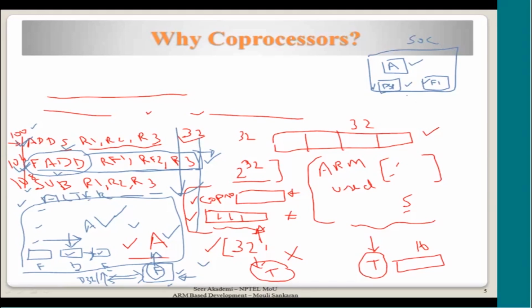They also keep a pipeline similar to the ARM core, a 3-stage pipeline, and they keep filling in the instructions they see while the ARM processor is accessing instructions from the memory. Typically coprocessors also run at the same main clock as the ARM core, and they are in sync with the ARM's pipeline. Have this background, as it will help you to understand the rest of the topic.